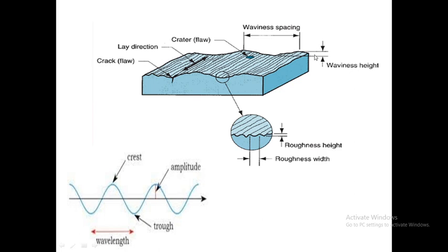Now this is my workpiece. The assumed ideal condition was that after machining, the surface of this workpiece, that is the top surface, should be exactly flat. But after the machining process, when the surface is observed under a microscope, we can see that the surface is not exactly flat, or it has some kind of roughness. This is because of various problems, such as machine vibrations, the various types of coolant used, the material used, etc. So, in short, the workpiece does not have a flat surface.